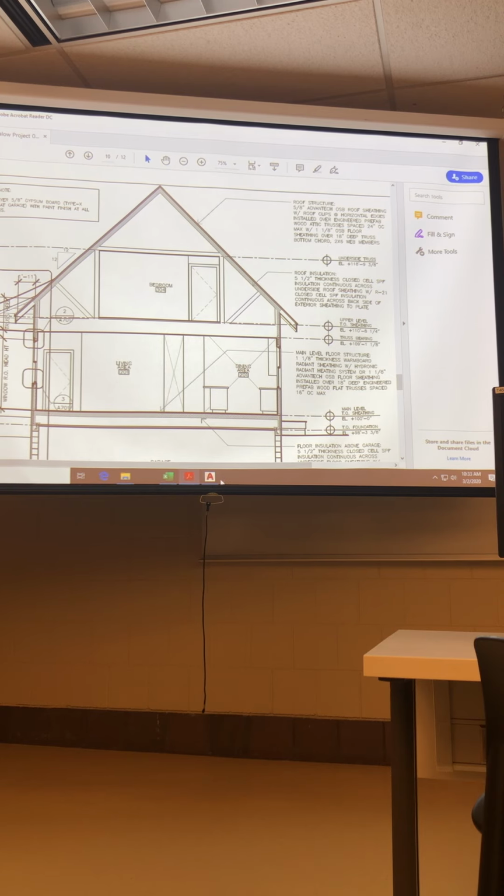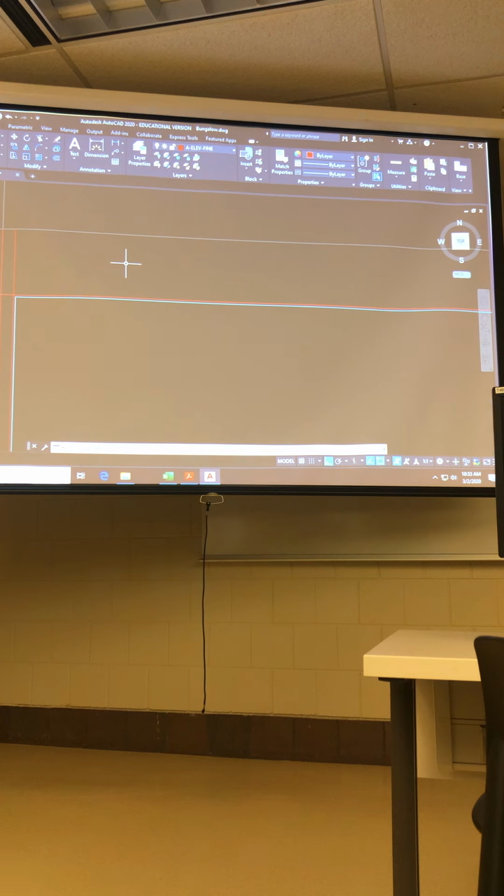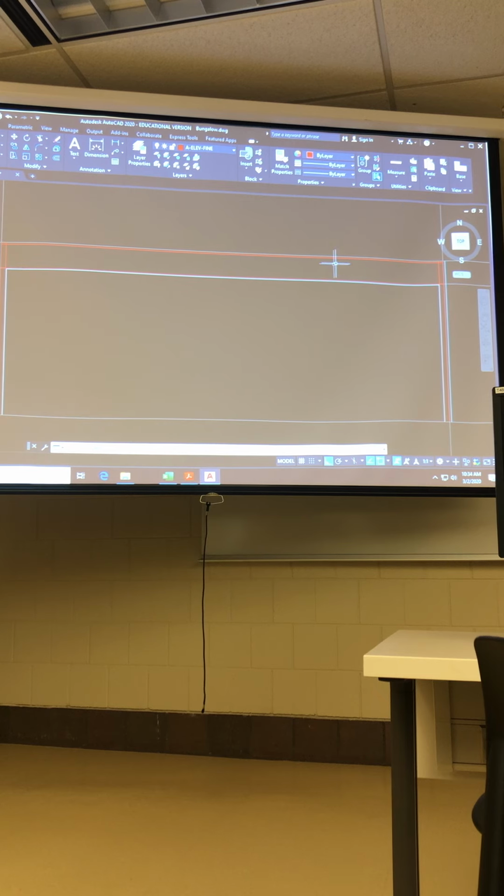So I'm gonna go back to my drawing and offset 18 inches from the bottom side of the bottom chord to the top side of the bottom chord. And there's the bottom chord of my truss, right? And from there, again, up to my datum elevation, that's the thickness of the floor sheathing for my upper level.